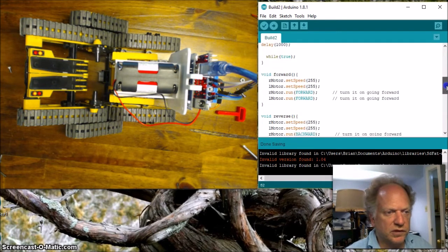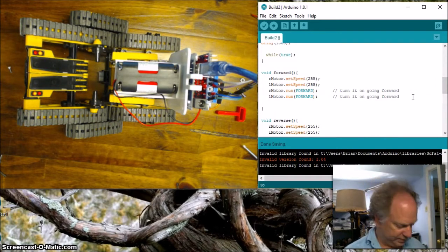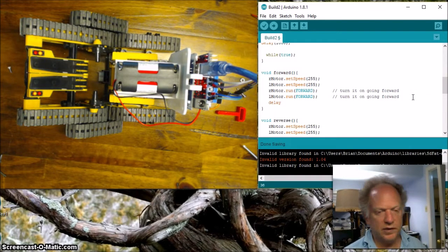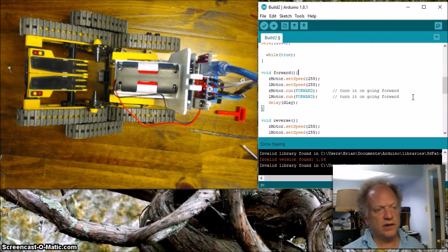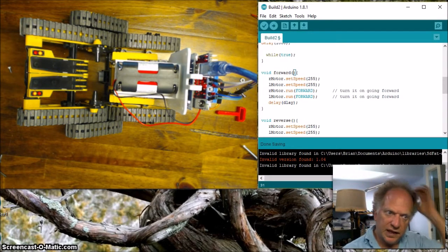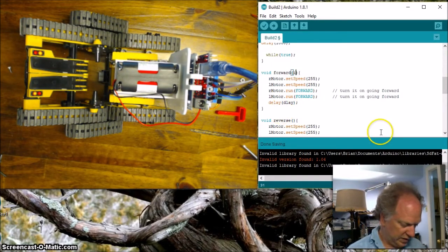Let's go down to the individual functions, and what I want to do is add the delay in here. And I think what I'm going to do is call it delay. Okay, a little funky spelling. And up here in this parentheses is where you could put something called an argument. And the argument I want to put is a number in here that will be passed down to the delay variable right here. So I'm going to create an integer variable, and I'm going to call it delay.